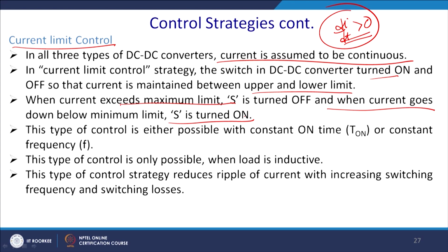It just operates in a band of hysteresis. It's like your AC: if you set it to, let us say, 25 degree centigrade, it will turn on when it is 25.2 and continue to chill down, and when your temperature goes below, let us say, 24.8, it will turn off. So, your bandwidth is basically 0.4 degree. It is something like this.